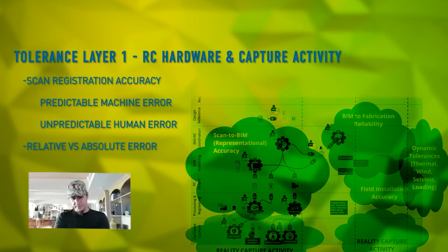So fundamentally, a laser scanner isn't that different from one of these things, which happens to be on 2 different motors, one that spins it this way and one that spins it really fast this way. That's basically what a laser scanner is in a nutshell. What that means is there's a bunch of different systemic tolerances associated with that. Laser scanners don't make perfect measurements. Nothing makes perfect measurements. And there's obviously a whole range of laser scanners on the market that have different tolerances.